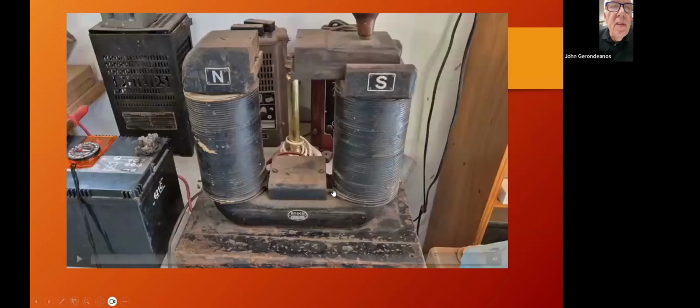And a cracked magnet will not hold a magnetic field, not for long anyway, and it'll always be weak. And once you've finished magnetizing your magnets, check them. Minimum 2 pounds that they can pick up. If you can pick up 4 pounds, I believe that a well-magnetized magnet can pick up as much as 9 pounds.